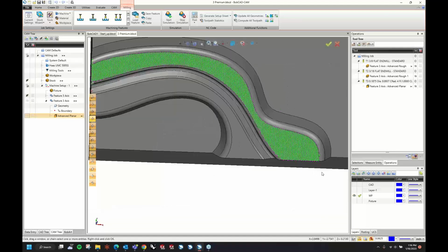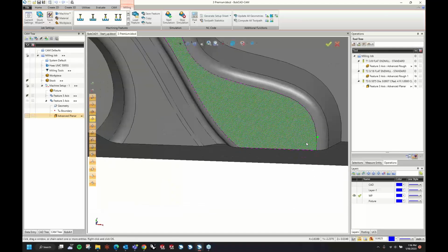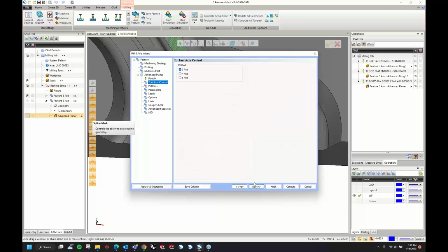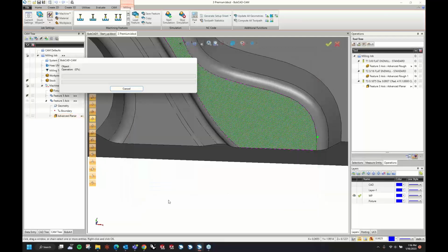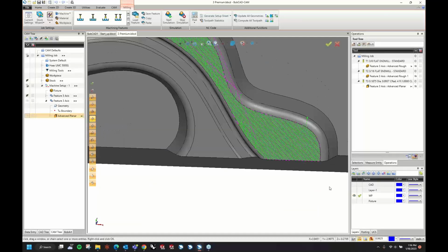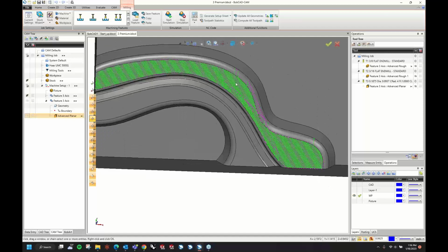So this actually follows it a little bit more, but it's really not following that shape. It's going to go across that shape. And then you can spend quite a bit of time playing around with this angle. I think I eventually went to 135 degrees before it had a decent flow with this channel here, but you can see it's retracting quite a bit.